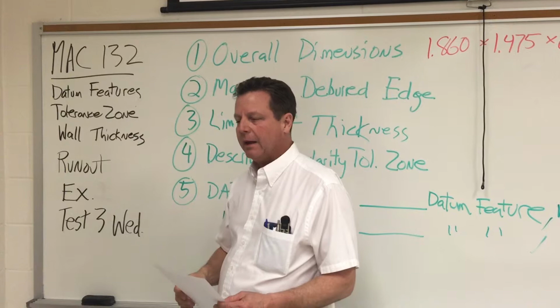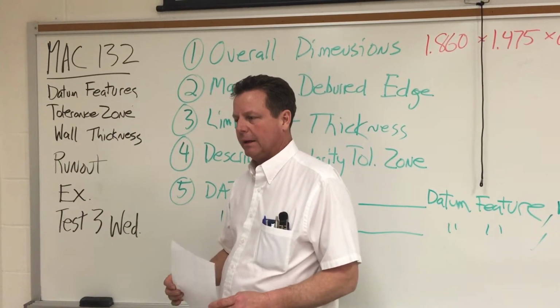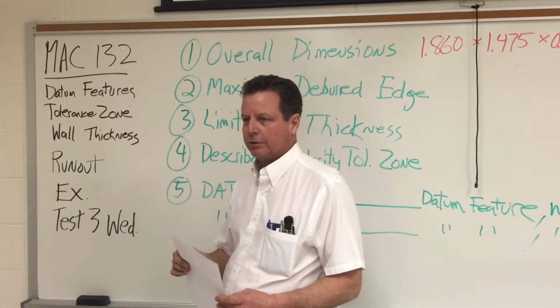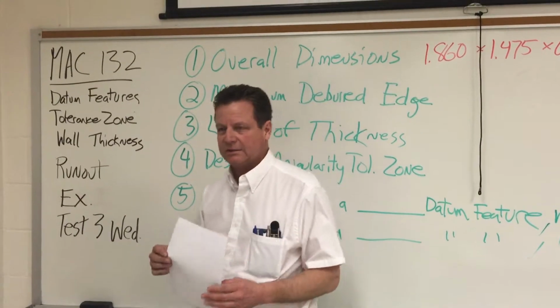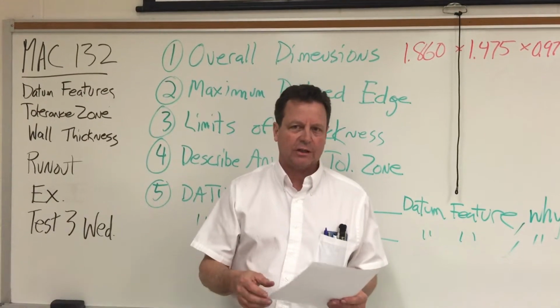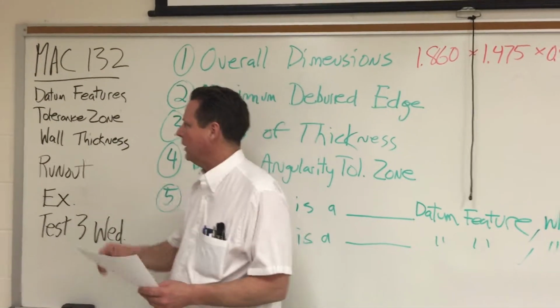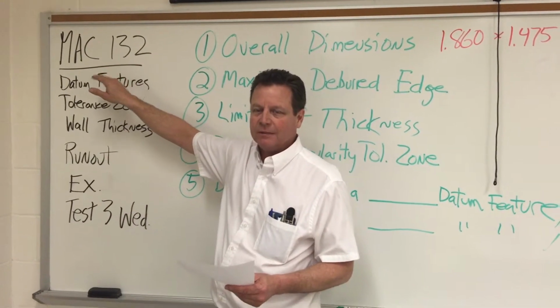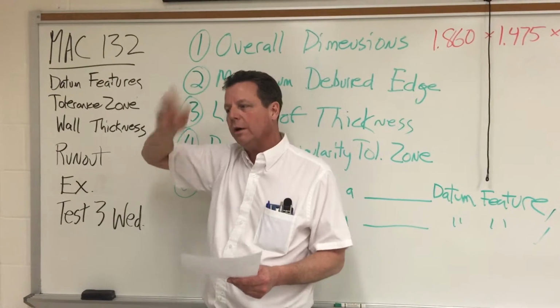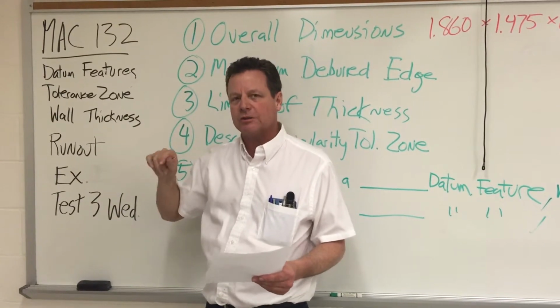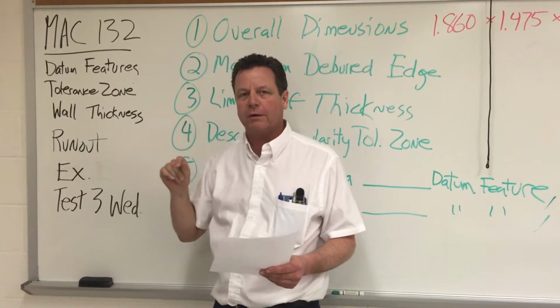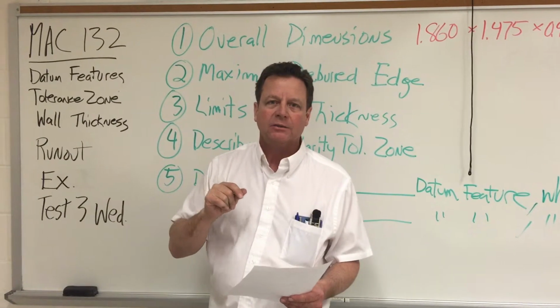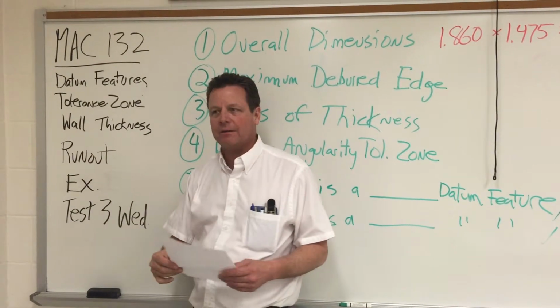Well, I handed back the retest and got a little bit better picture of what is and what isn't sinking in basic GD&T. And what I determined was we aren't understanding what a datum feature is. A datum feature means what is serving as the datum on this part. Which feature of the part is serving as the datum? So we had to think about that for a while.